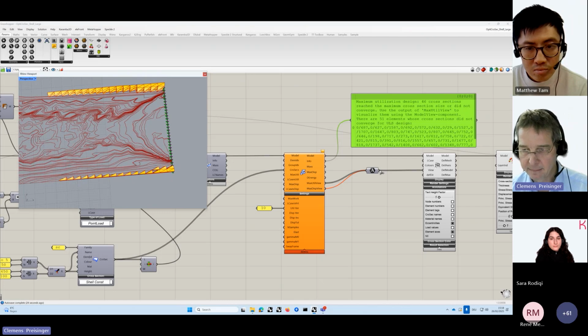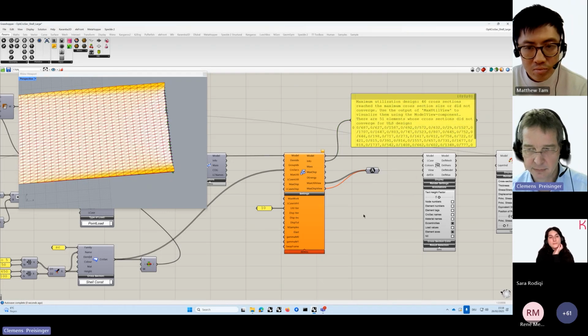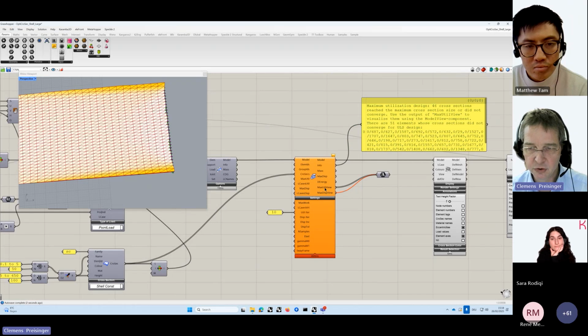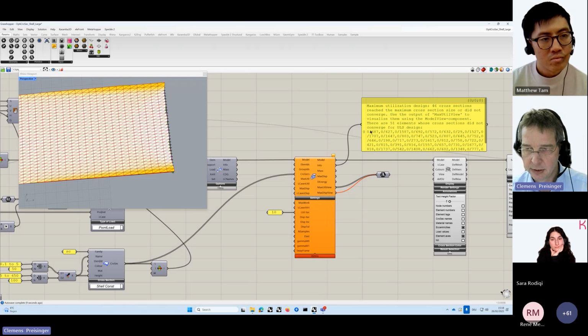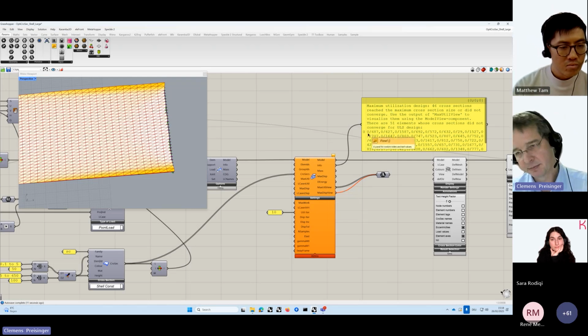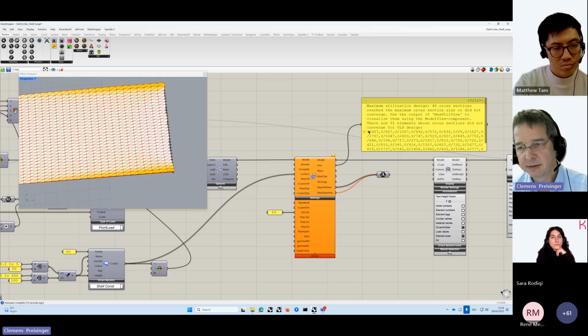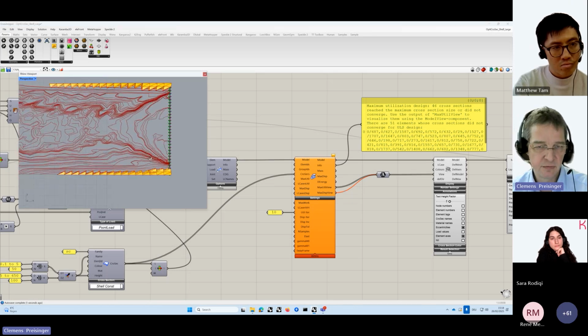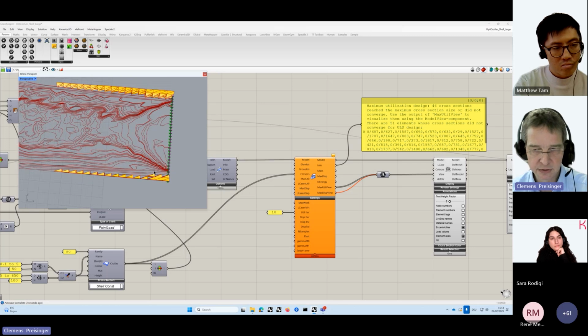And now there is the option to visualize which elements cause this message. So there is a special notation. So if element number 0 is a shell, then you can supply here the index of the face, which shall be visualized. In that way, you can see where there are problems in the structure.